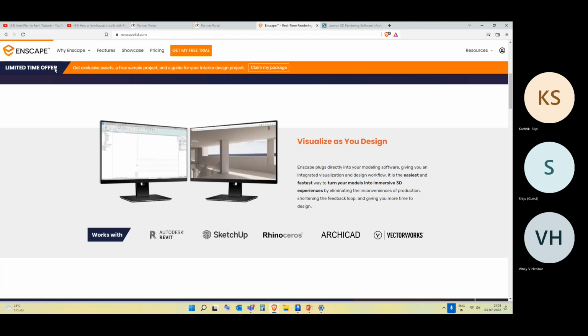The beauty over here is this Enscape can be directly plugged to the VR headsets. Once we've done our modeling, we can push the whole model to Enscape, and from there we can connect our VR headset and show our clients how the building is going to look, or judge the choice of material, or whether the building is going to fit in the vicinity or not.